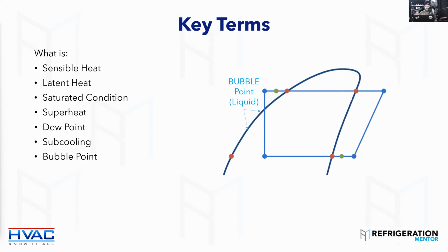Well, while we're waiting for, oh, there you go. I was just going to say that with these charts, you can actually take your system readings and plot them on the chart. Each one of these charts has its own refrigerant from what I remember. And these are actually really good troubleshooting charts. If you're having trouble with a system, you take your readings and plot them on this chart, and you can actually see what it's doing and get a full visual of the entire system. 100%.